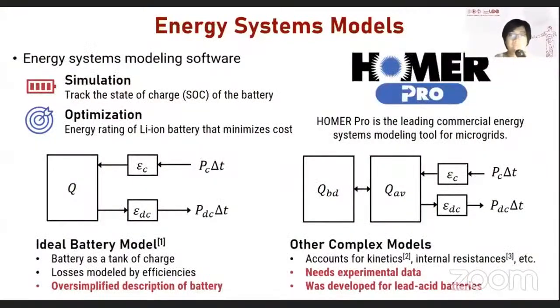Now, the deployment of lithium-ion batteries in renewable energy systems is studied using energy systems modeling software, such as HOMER Pro, which is the leading commercial energy systems modeling tool. This software has 2 important tasks. First is to simulate the battery by keeping track of its SOC or state of charge. The SOC is defined as the charge in the battery divided by the maximum charge that you can store.